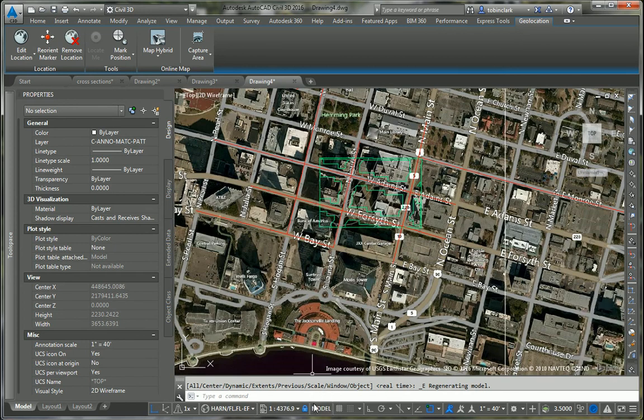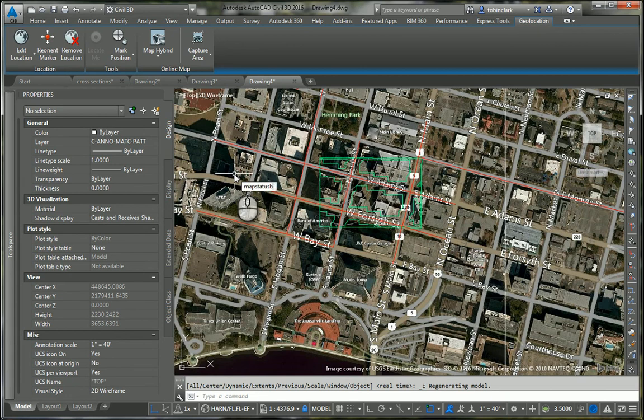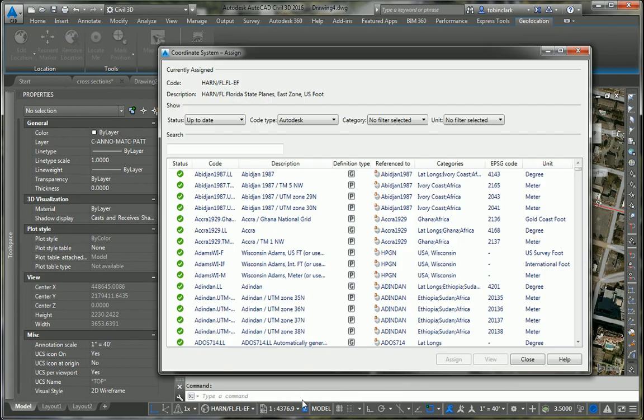So I'm gonna go back and look at this map thing, because that probably flew over your heads. Type in map status bar. Mine's on show. You need to set yours so it's on show. It's a setting. It's kind of cool. It lets you see your coordinate system without having to dig into AutoCAD settings, which is nice because we don't like digging all over into AutoCAD settings. You get this pretty pop-up.